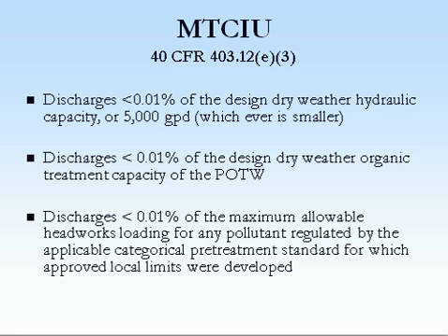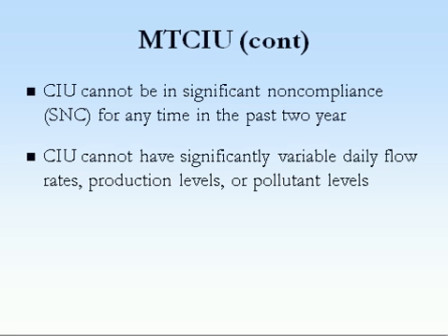or any pollutant regulated by the applicable categorical standard must not exceed 0.01% of the maximum allowable headworks loading that was established and approved in the local limits for that pollutant for that POTW. Again, the industrial user's total categorical wastewater process flow must not exceed any one of those preconditions in order to qualify for MTCIU.